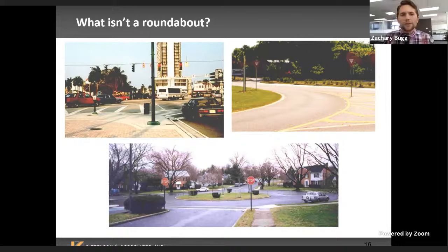Right, exactly. Traffic signals are really good at controlling priority and how much time you give to each movement. But the problem is once you have different signal phases, you've got what's called lost time, for those of you that maybe have covered that in your transportation classes. Lost time is time that nobody is moving through the intersection.